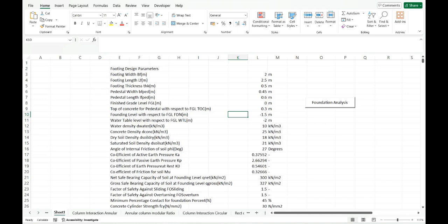Based on the maximum cantilever distance of footing slab from face of pedestal, the bending moment at face of pedestal is calculated for tension bottom case using this uniform net bearing pressure. With this moment, required area of reinforcement at bottom is calculated. Another approach is used here for calculating actual one-way shear stress and area of reinforcement at bottom. Here the user defines net maximum pressure for which the footing must be designed. Same procedure is adopted for calculating shear stress and reinforcement.